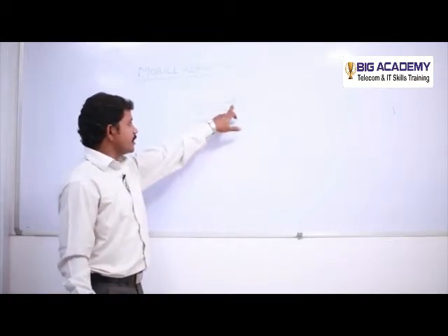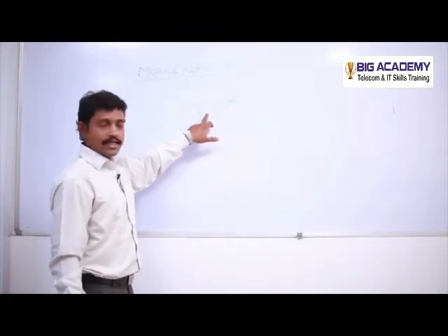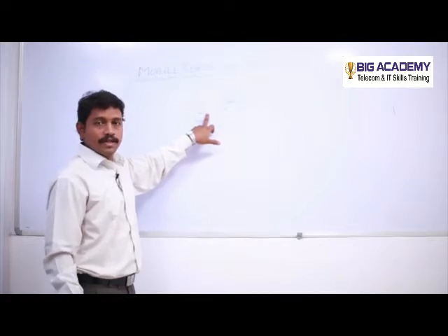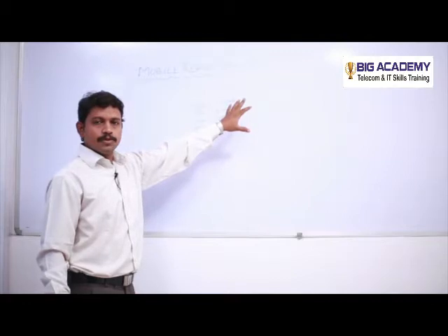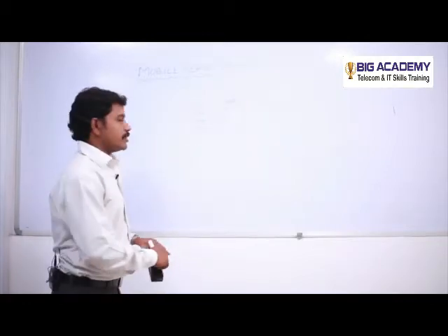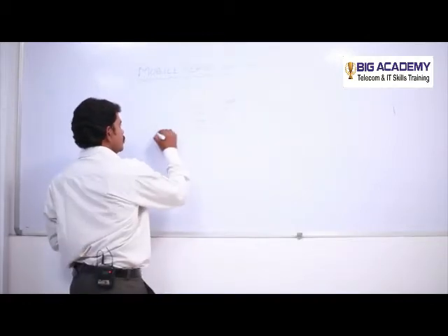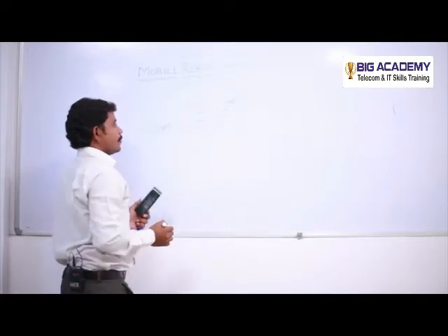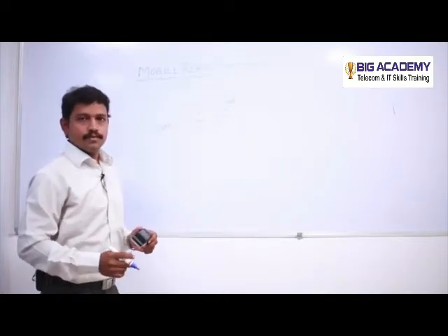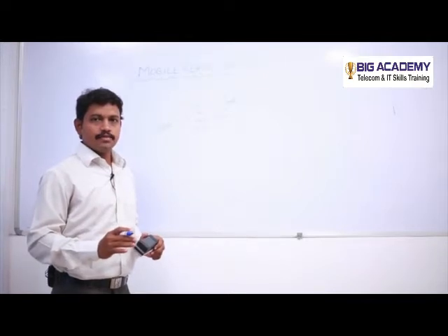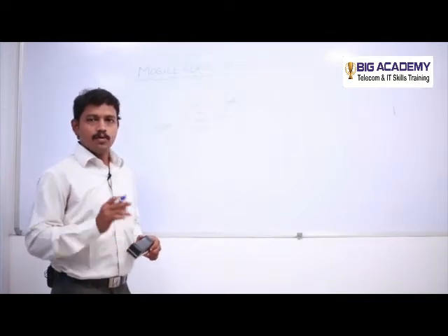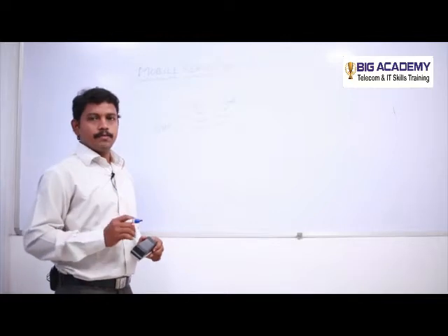Even if the ground connection is not proper and the voltage connection is properly connected, that will never give the exact output, right? So you should know the connections where the voltage pin is exactly pointed out and where the ground connection is exactly pointed out.